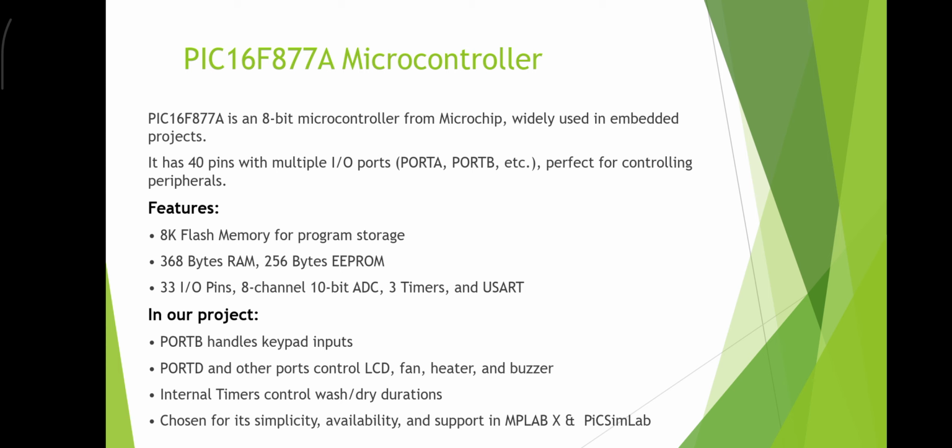The PIC16F877A microcontroller is an 8-bit microcontroller widely used in embedded projects. It has 40 pins with multiple input output ports, port A, port B, likewise. So it's perfect for controlling peripherals. Its features include 8K flash memory for program storage, 368 bytes RAM, 256 bytes EEPROM, 33 input output pins, an 8 channel 10-bit ADC, 3 timers and USART. In our project, port B handles the keypad input.